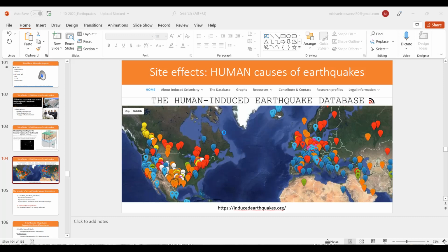So like I said, the modified Mercalli intensity is based on what you, the population, feel and what you, the population, report. So the USGS, as we talked about, has this Did You Feel It program where you can log in and say, oh, I felt this. This is what it felt like. This questionnaire is targeted to somebody who doesn't understand how earthquakes work. So they'll ask, how long did the shaking feel like it lasted? Or where were you when it happened? Very simple questions that they can get a lot of qualitative data out of.